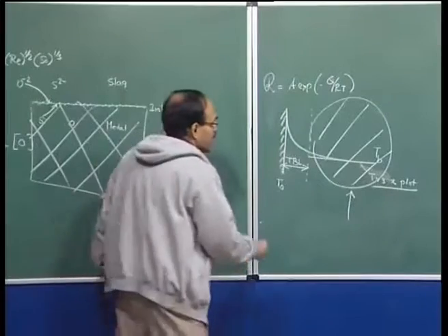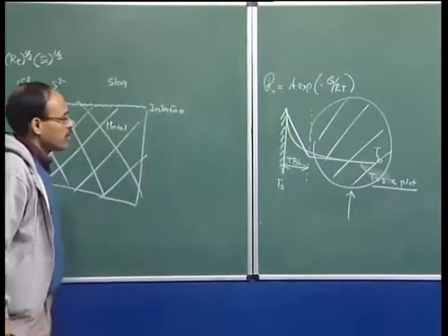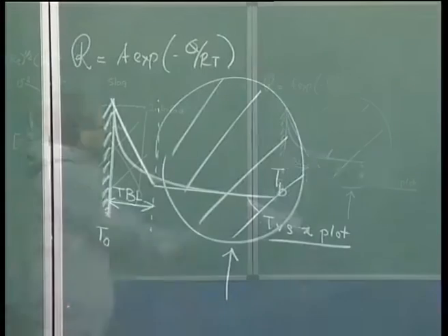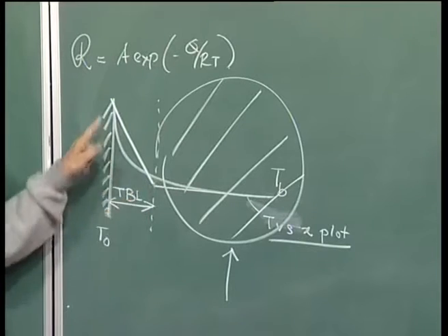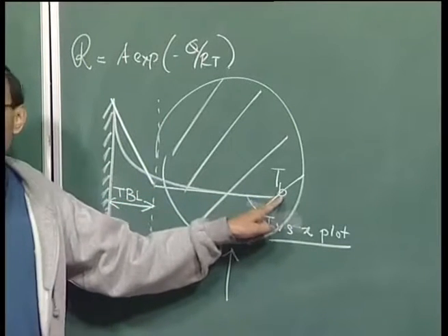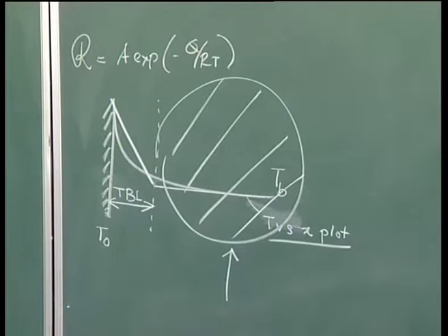The largest gradient really occurs within the boundary layer itself. So, the actual curve is then idealized in this particular fashion, and we see that between the edge of the boundary layer and the bulk there is no drop, and that is how we determine the temperature also. Now, we are going to see how this concept carries over in the case of mass transfer.